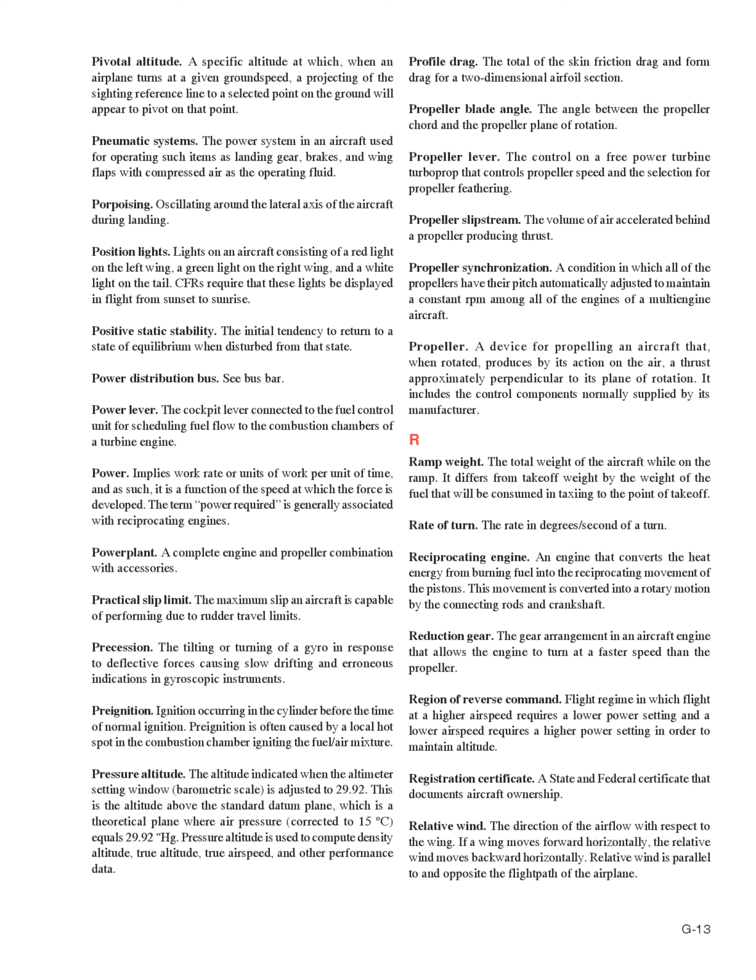Profile drag. The total of the skin friction drag and form drag for a two-dimensional airfoil section. Propeller blade angle. The angle between the propeller chord and the propeller plane of rotation. Propeller lever. The control on a free power turbine turboprop that controls propeller speed and the selection for propeller feathering. Propeller slipstream. The volume of air accelerated behind a propeller producing thrust. Propeller synchronization.